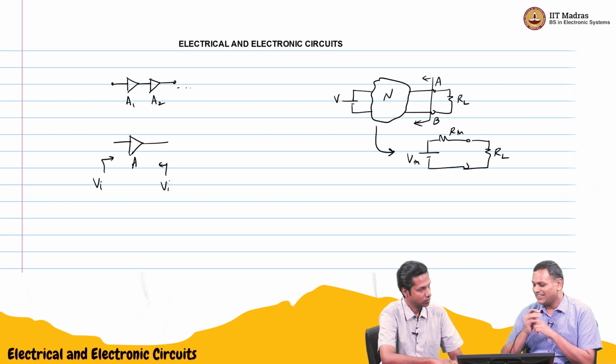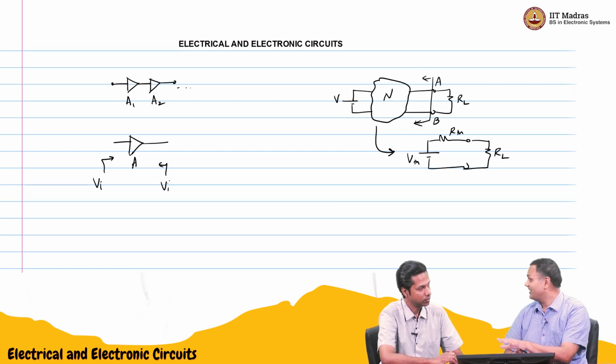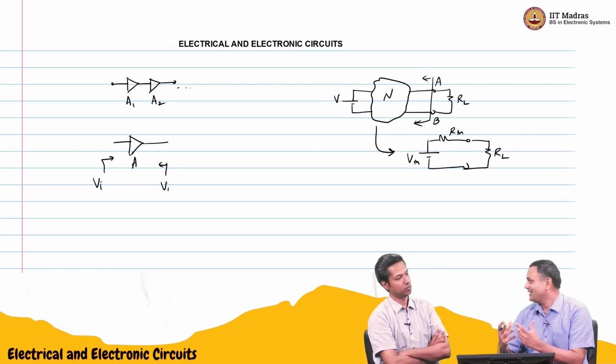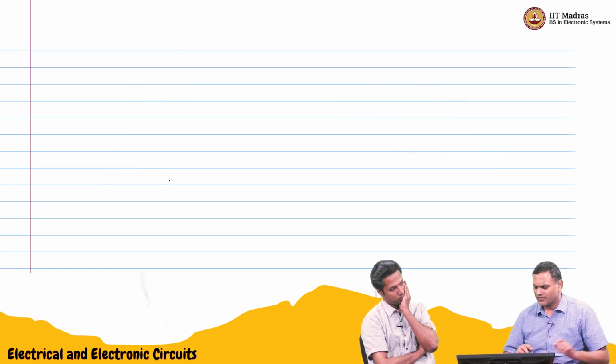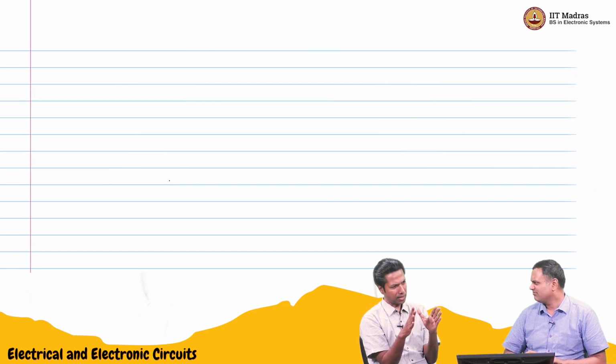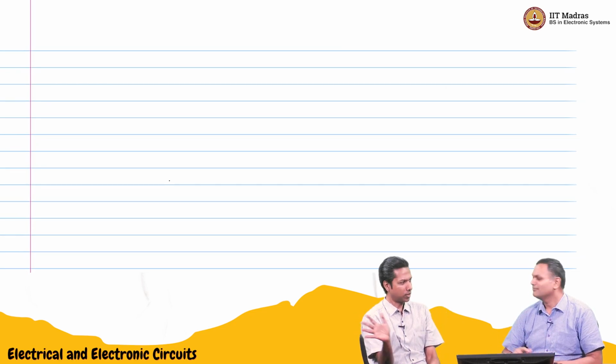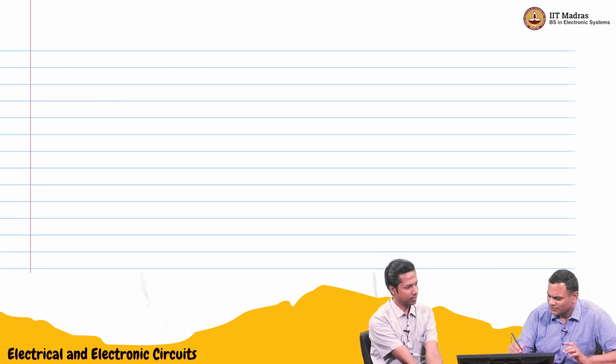So the way I think of the Thevenin equivalent, you have the electrical information, voltage and current and impedance and so on, but you don't know what the structure looks like inside. It's kind of an abstract form. There can be many networks which have the same Thevenin equivalent. So basically it can be some black box: from the input, how it will look, and from the output, what the parameters are.